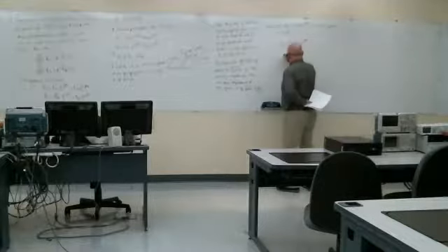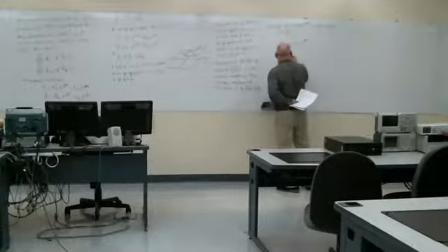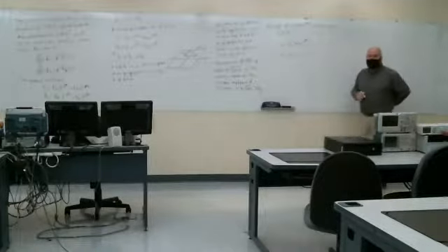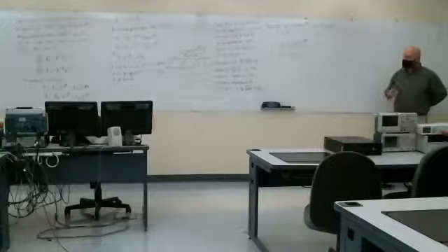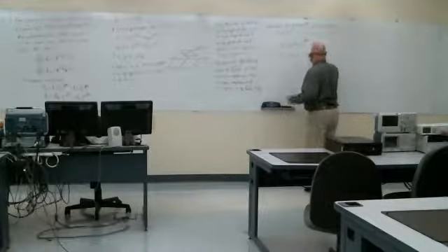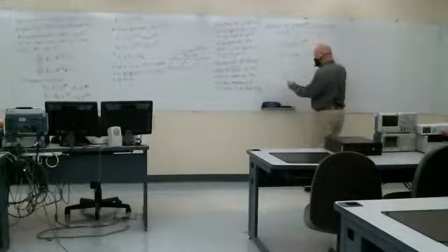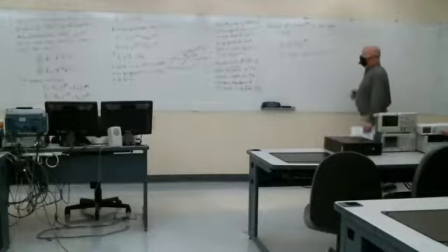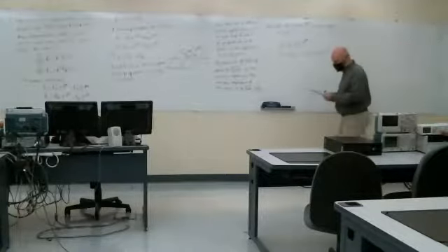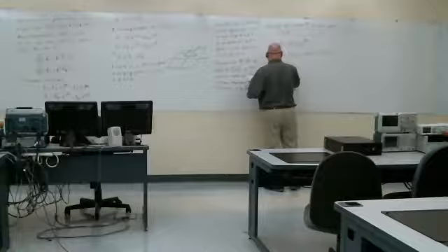And then I can also find the amplitude here. It's 10 over the intrinsic impedance. Might remind you of Ohm's law. In this case, since it's free space, it's 10 over 377, or 0.02653, and it would be amps per meter here, actually, since the 10 would be in units of volts per meter.